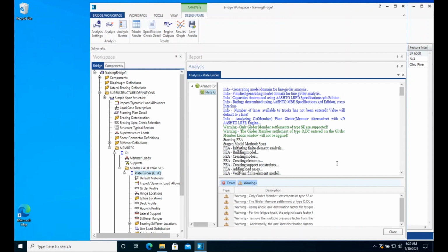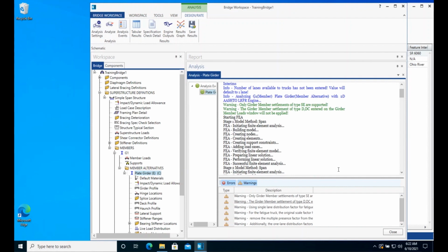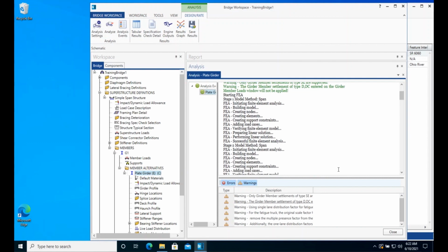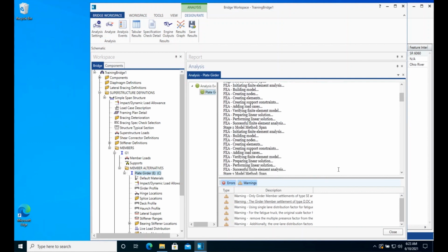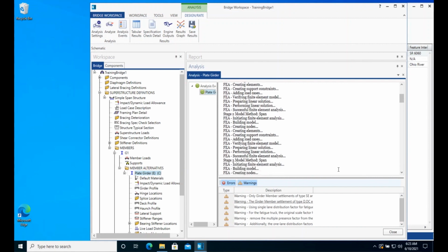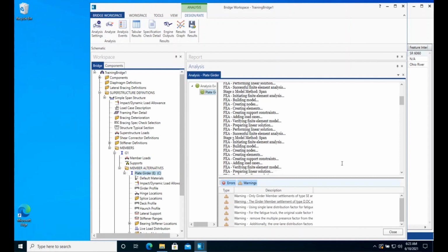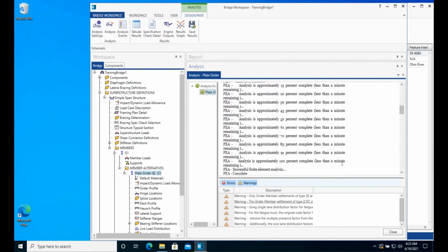The basic steps of the AASHTO analysis engine computation process are as follows. User input data describing the girder member is used to generate finite element models for each stage of the member, such as the non-composite and composite stages. The dead loads present in each stage are applied to the FE models and the resulting unfactored dead load force effects are determined. Live load influence lines are generated for analysis points along the girder using short-term composite section properties.